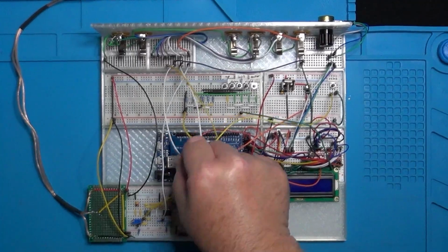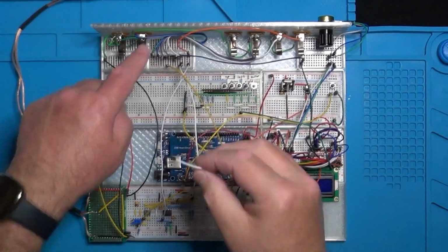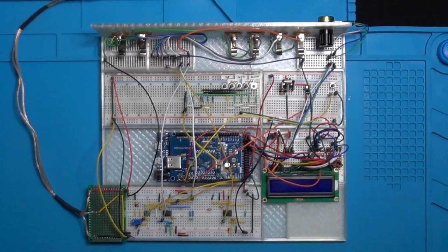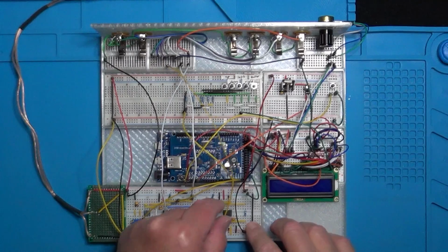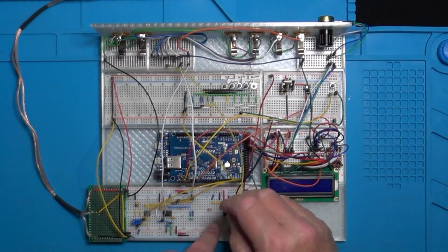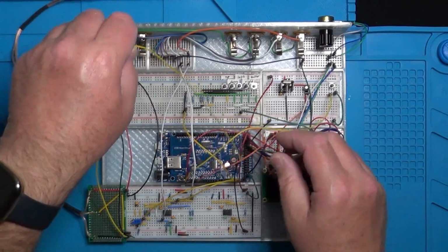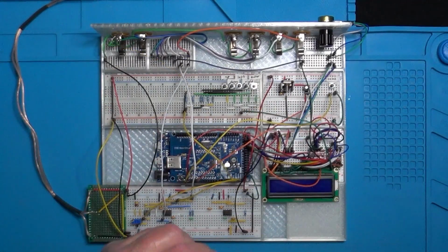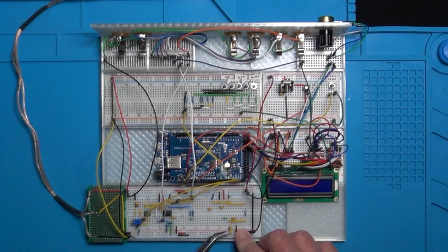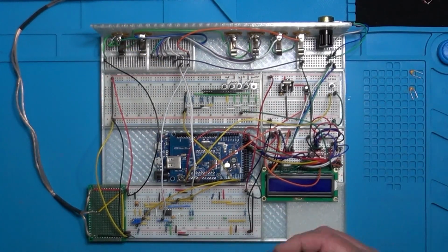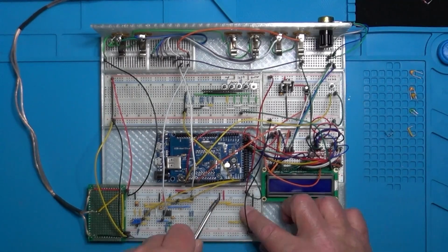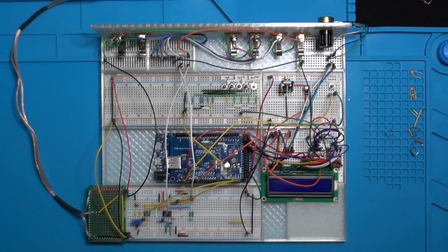Let's now make these changes and then let's run a few tests, first in the lab and then at the Synth. First, let's remove the wire that connects the circuit to the jack socket, and also the wire that connects the gate output to the input of the trigger circuit. Then we remove the IC and all the other components and wires that make the hardware circuitry for the trigger.